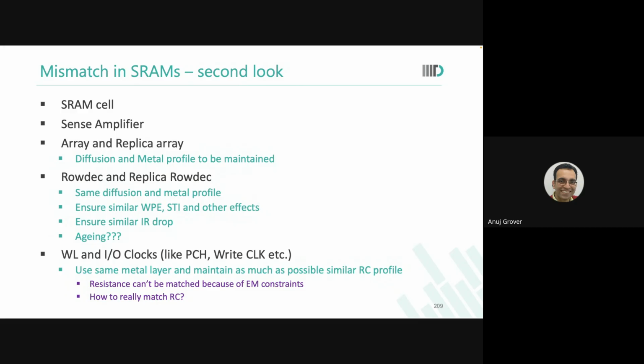Oh, in this particular row, the connection to the bit line is broken. That VIA doesn't exist. So this is my replica bit line, a replica line or replica column, and things like that. So you have to go into that detail to be able to identify which one is the replica. Otherwise, everything else is same. All metal, all the topology is exactly the same.